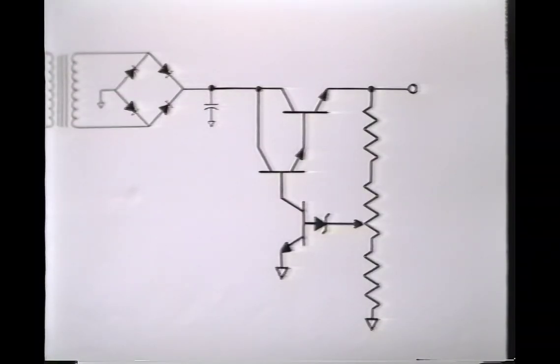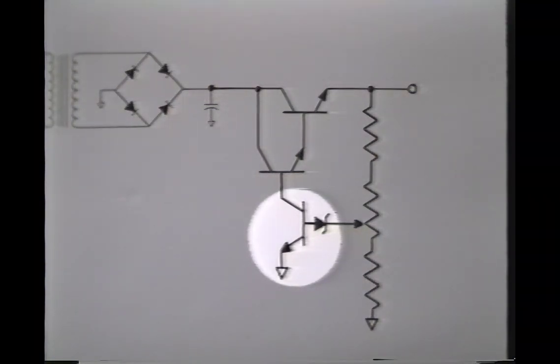This circuit is typical of those that we'll find not only in the pinball machines, but also as the power supply regulator circuit in monitors as well. It's a standard series pass regulator circuit with a regulator transistor and a driver transistor in a Darlington setup, but instead of using the integrated circuit, we use a transistor and a Zener diode.